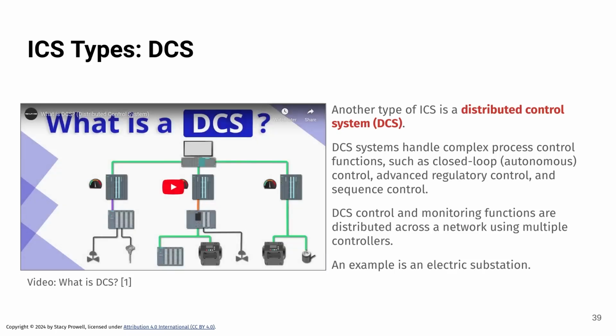It's distinct from another kind of system called a distributed control system, or DCS. And that's typically what we would call a closed loop control, right? SCADA has an open loop with a human in there, right? So commands go out, sensor readings come back, but they don't close the loop. The sensor readings don't directly affect back to where the commands are. There's a human being in there seeing all this stuff and taking action. And that was what makes it supervisory, a SCADA system.